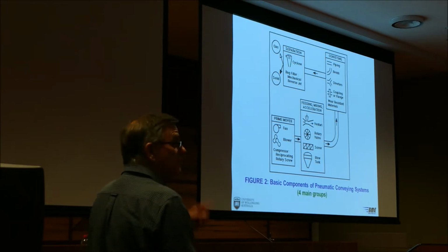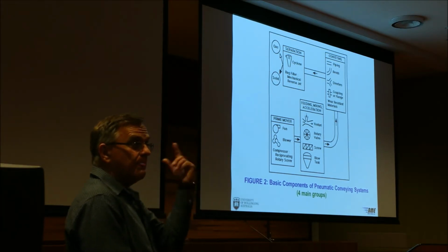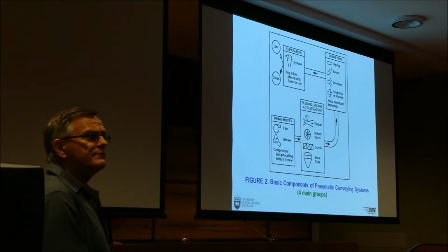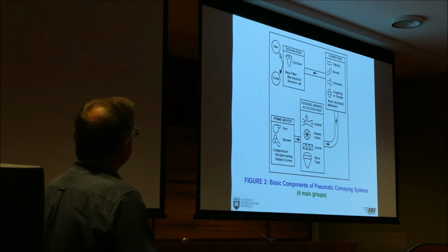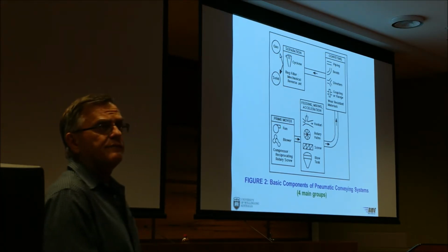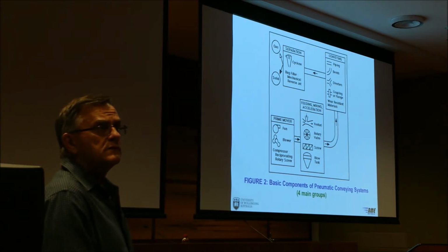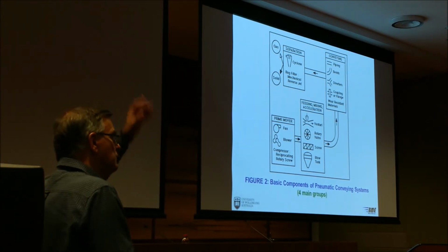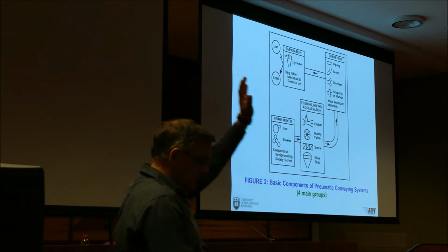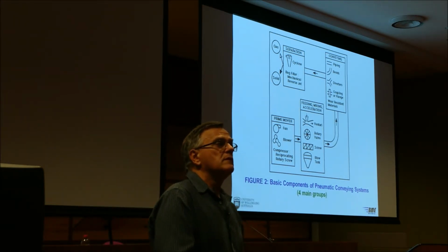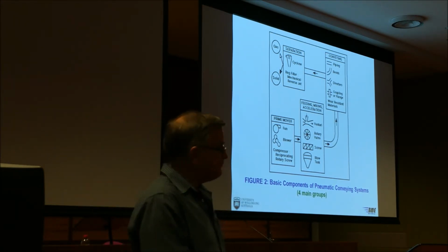We can use a cyclone, centrifugal separator, but they're not that efficient, particularly with fine powders. So generally we need a filter of some form to filtrate the air, like to clean the air. And so you've got all your air going out and all the particles going into the silo or process.